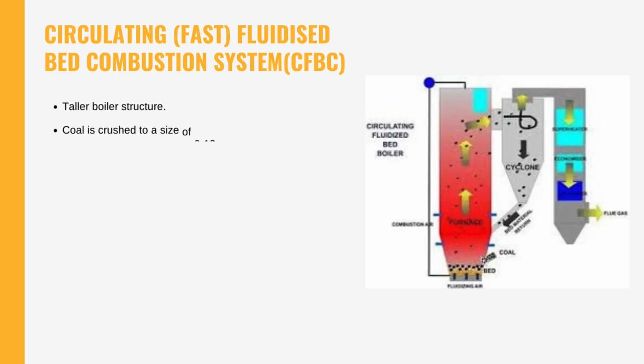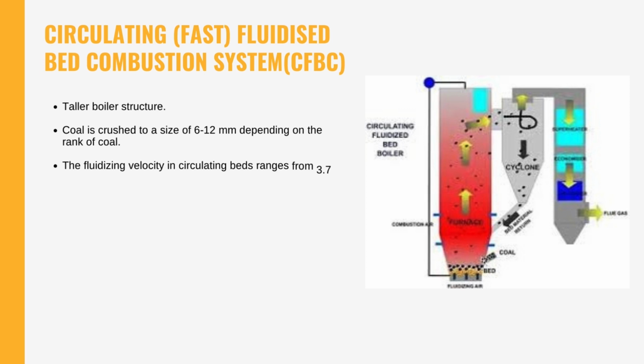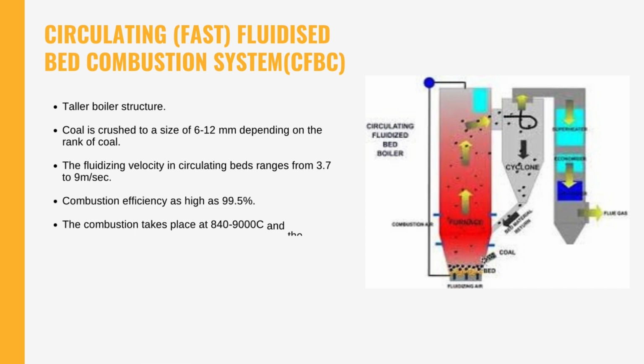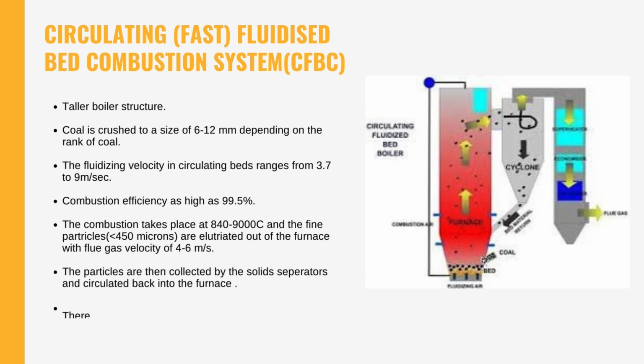Now we will discuss the second type of FBC, circulating fluidized bed combustion, CFBC. The circulating fluidized bed combustion technology has evolved from conventional bubbling bed combustion as a means to overcome some of the drawbacks associated with conventional bubbling bed combustion. This CFBC technology utilizes the fluidized bed principle in which crushed fuel of 6 to 12 mm size and limestone are injected into the furnace or combustor.